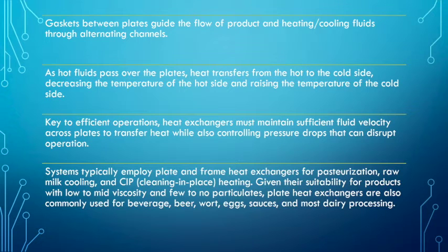Key to efficient operation, heat exchangers must maintain sufficient fluid velocity across plate to transfer heat while also controlling pressure drop that can disrupt operation. Systems typically employ plate and frame heat exchangers for pasteurization, raw milk cooling, and also CIP or cleaning in place heating.